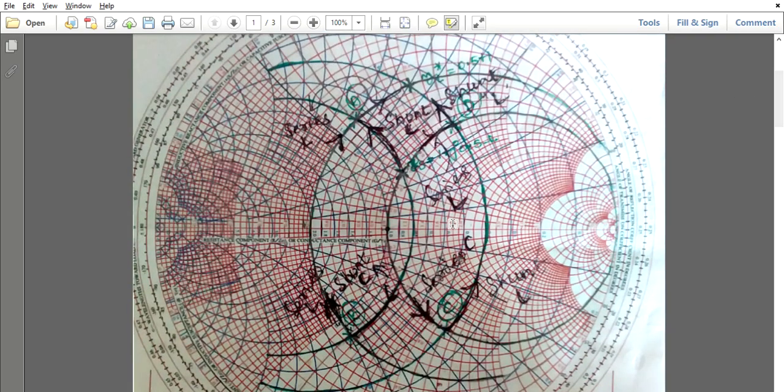For example, if it is B, right? You take the B intersection point. What is the condition? You have to start from ZS, go through the B intersection point, and you have to end at ZL, right? So the arc for the B intersection point: ZS is the starting point, it goes through B, and it should end at the ZL point.